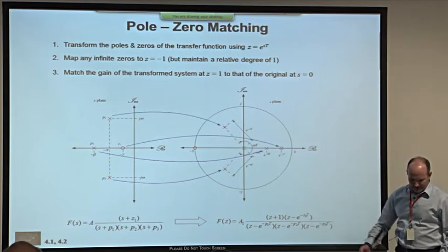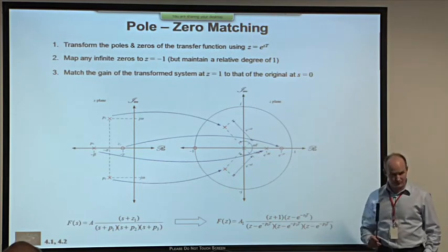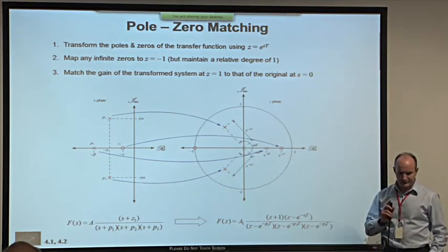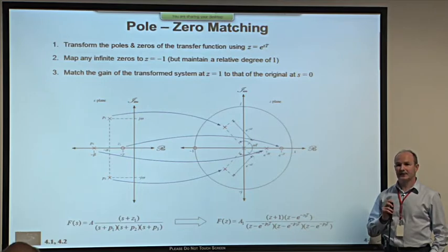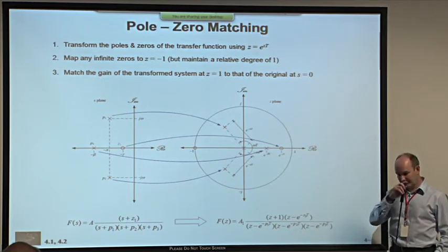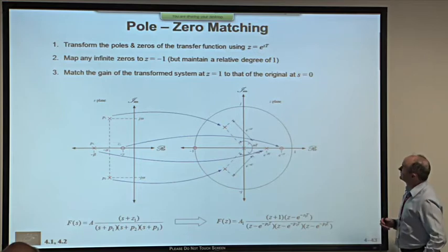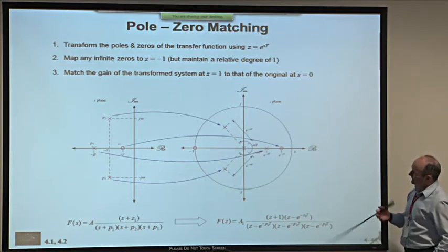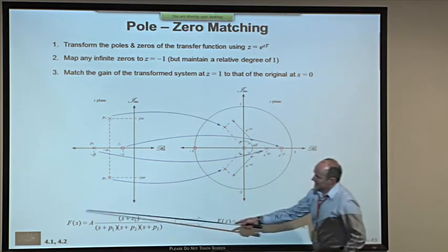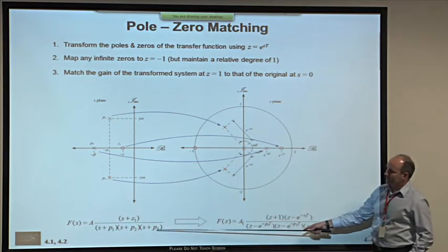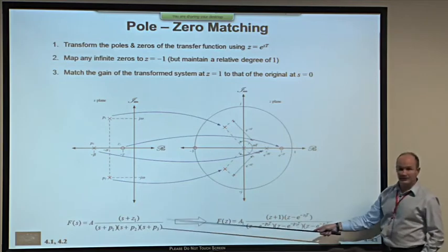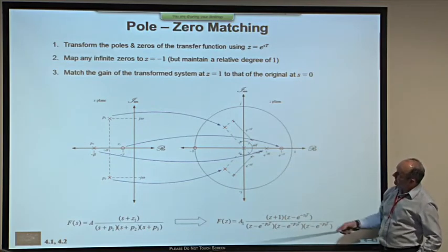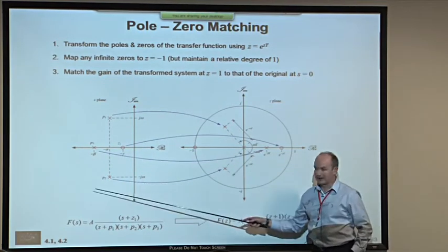Its main drawback is that one of the rules obliges us to impose a one sample period delay in the calculation, and that time delay adds a phase lag, which is a little bit unfair, but let me show you the method first, and then you can be the judge of whether it's suitable or not. I'm going to illustrate it for this third order system down here with Laplace transform A as a sum gain times (s plus z1) divided by all that lot. So we've got 3 poles and 1 zero to transform, and here is the pole zero map in the S-plane.